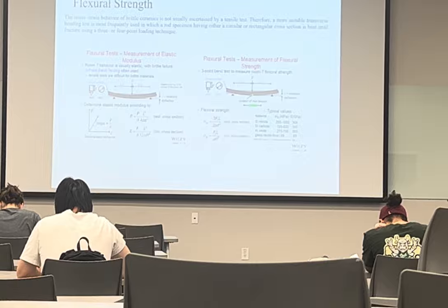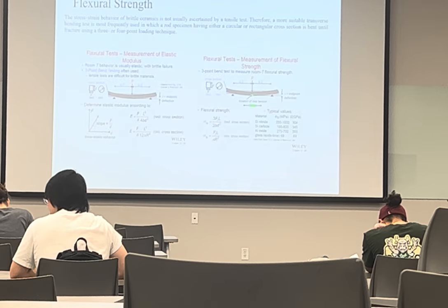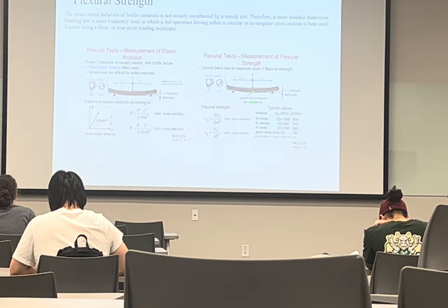In this test, the most compression is going to be where we apply the force, and similarly, the most tension happens at the bottom surface.